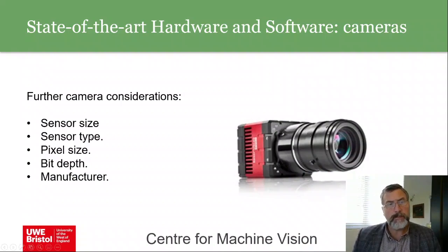Sensor type, well, traditionally that's meant a choice between CCD, or charge coupled device, and CMOS electronics, which produce lower voltage devices and what you might find in miniaturized devices. In your phone, you're going to have a CMOS. Years ago, CMOS wasn't as good as CCD. They used to be a bit noisy, but they've come on so much. The quality of some of the sensors nowadays in mobile smartphones is pretty amazing, and they would generally be CMOS, so it's come on a lot.